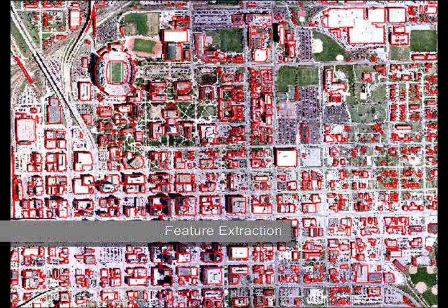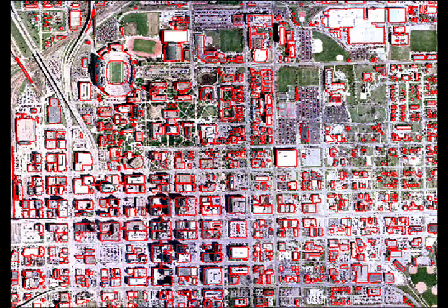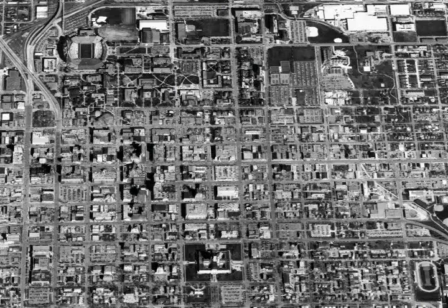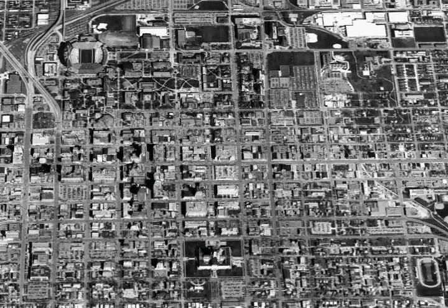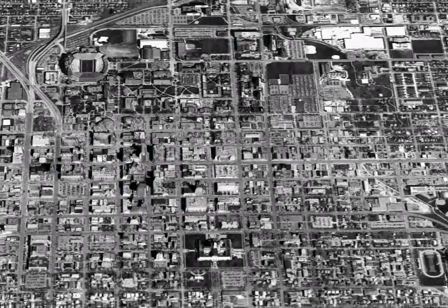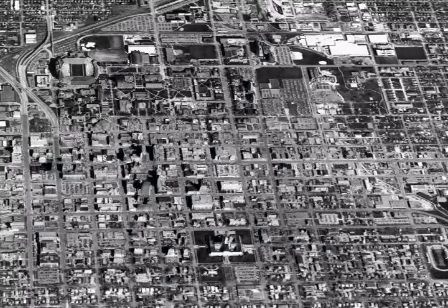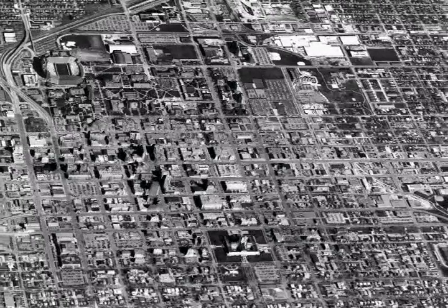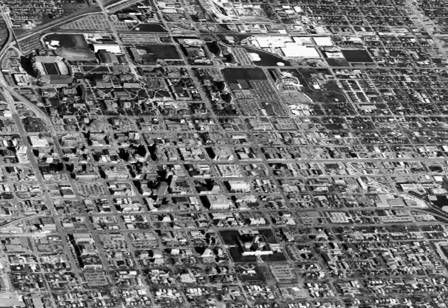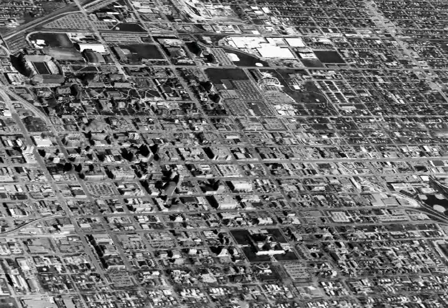For example, using LiDAR data, building footprints can be delineated by successive classification and eventually extracted as vector features. This technique is not perfect and requires additional processing in most cases, but is generally less labor-intensive than many traditional methods, such as digitizing from orthorectified imagery. These extracted features can also be recombined with bare earth terrain and draped imagery, producing a very realistic three-dimensional representation. Among other fields, three-dimensional city models are useful for emergency management.